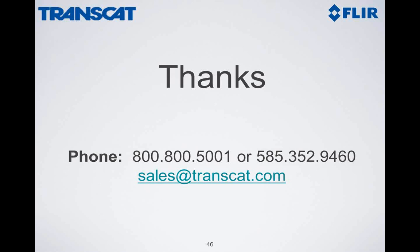I've known customers in doing electrical work, when it's the end, wrap it around the bus bar or an electrical item. But also, you can find many cavities as well. As we described, the cavities act almost like a perfect emitter. So that gives you the ability to artificially raise the emissivity and get a good temperature measurement.